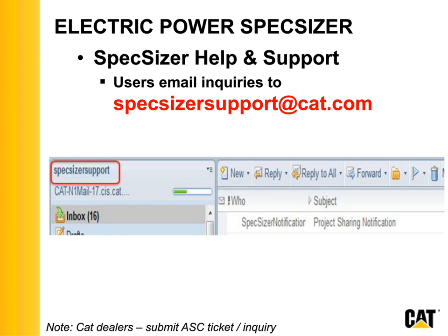If you understand your application, and we talked about duty point percent, you need to understand duty point percent. If you've got a motor and a load factor, say you have a 10 horsepower motor and you only need it to be 10 horsepower when it starts, but you only need it to be at 60% when it runs, so 6 horsepower, that's your load factor. Well, you can reduce your load factor or your duty point percent. And so there are things that you can do to reduce your inrush, to reduce your running, to reduce your harmonics, and we talked about all those.